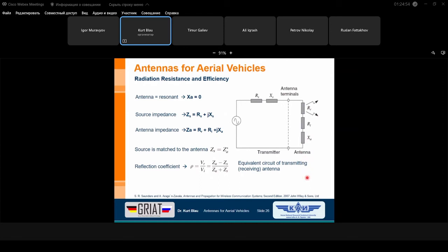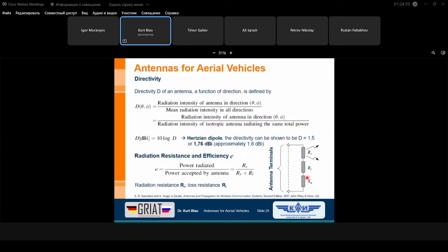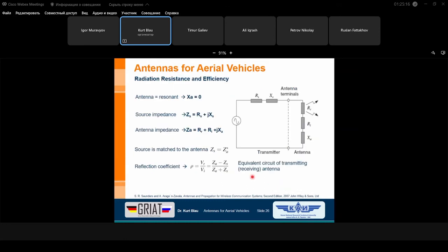As you know, it's very important for determining again the efficiency of an antenna, to find out the relation between radiation resistance and the sum of radiation resistance plus loss resistance, and then, together with what our generator delivers to the antenna, meaning if we can ensure that the delivered power from the generator goes completely into the antenna, or a part of it is reflected back.